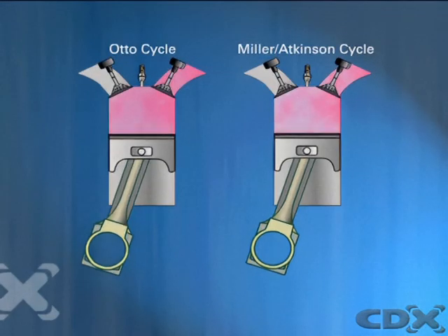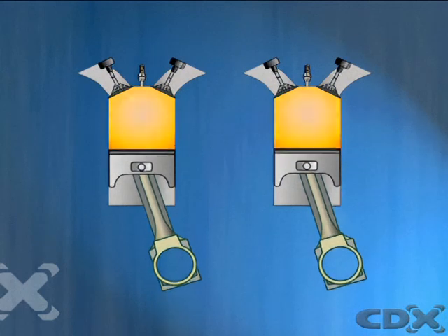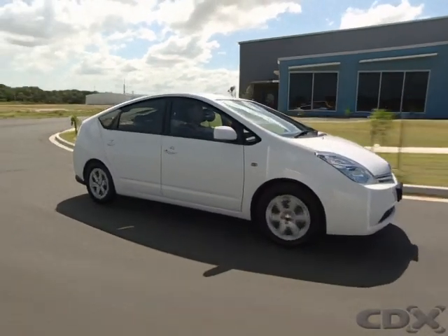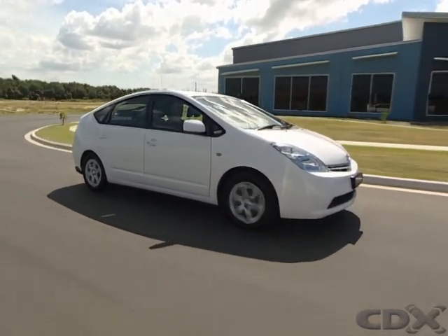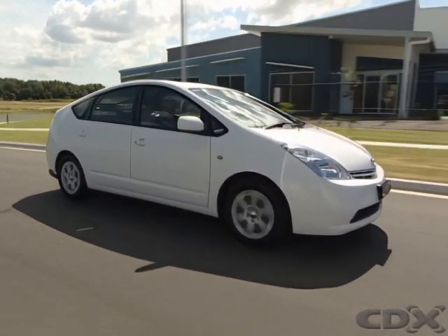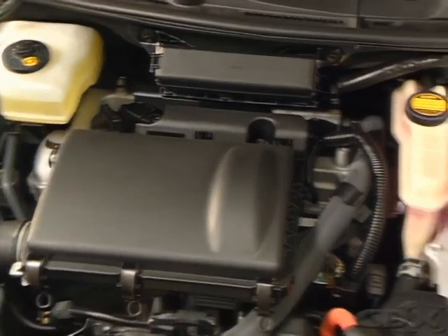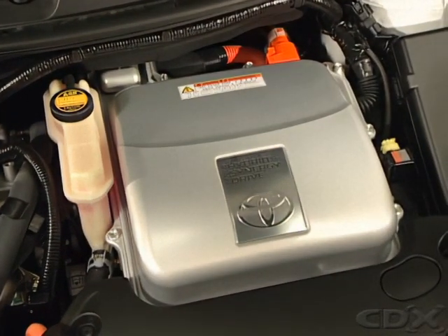The Atkinson cycle engine is efficient within a specific operating range, typically between 2,000 and 4,500 rpm, but its power output and torque are lower than a conventional engine. This type of engine is less useful as a primary power source, but is ideal in applications such as a series parallel hybrid vehicle, charging and working in tandem with a battery-driven electric motor.